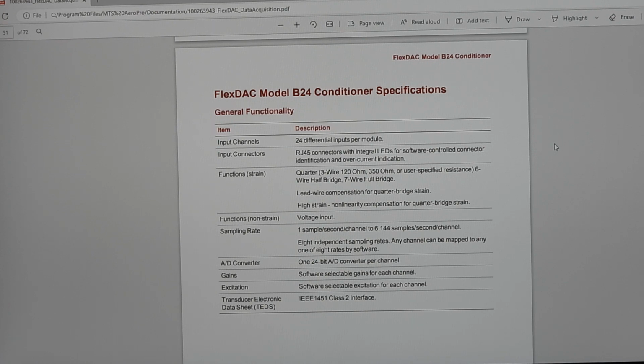I think you need external conditioning to bring that into DC, not just AC excitation, but also specific pulse processing. Is it amplitude modulation that you get out of that? You have to do some phase correction, because I think the amplitude of the AC signal that you get back is proportional to your displacement.